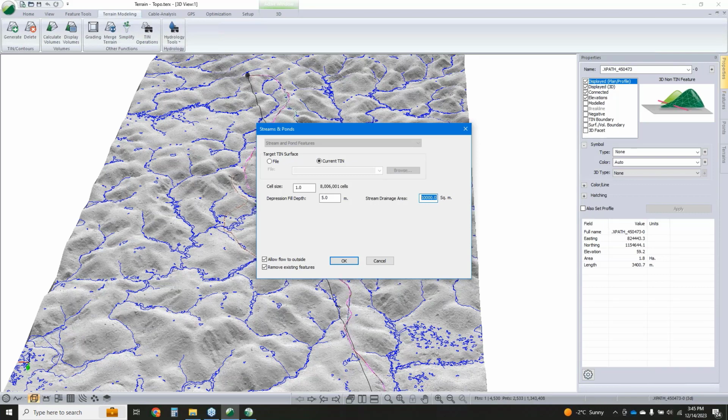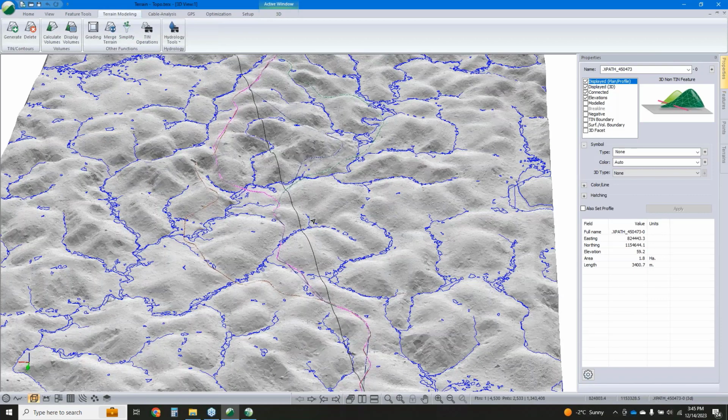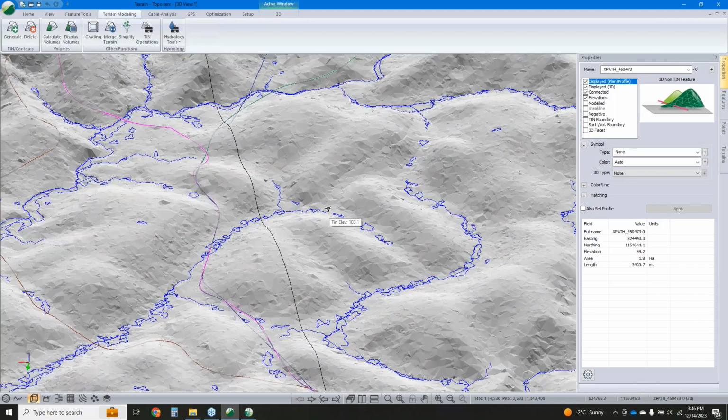As you're getting your feet under you, the best way is to kind of try it iteratively. It runs pretty quick, and do that sanity check of, okay, that makes sense that in this case our streams are crossing here. Whereas if we went with a smaller number, well, the streams are going to extend further up into the watershed. So from a practical standpoint, just calibrating it based off of the typical conditions in the area that you're working is the most appropriate.